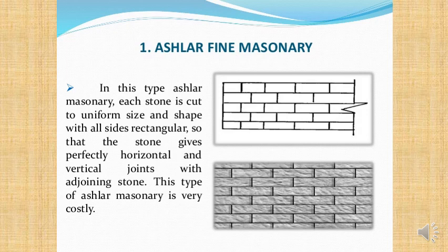So the material will be more expensive, but it's also going to mean you're going to have cheaper labour. I would much rather build a wall if I was the labourer using ashlar masonry than rubble masonry, because effectively all of the courses, every time I lay a course, I will have a nice flat surface where I can place the mortar, and then I can put the new course on top of the mortar. It's a lot easier.